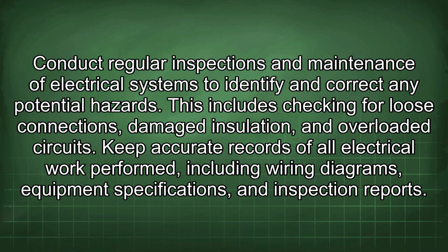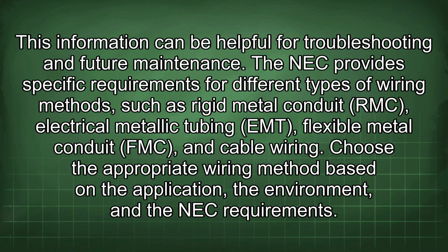This includes checking for loose connections, damaged insulation, and overloaded circuits. Keep accurate records of all electrical work performed, including wiring diagrams, equipment specifications, and inspection reports. This information can be helpful for troubleshooting and future maintenance.